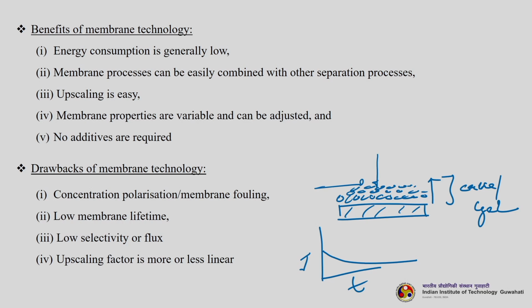So, by all these things the membrane lifetime is getting reduced, and selectivity or flux is a concentration polarization or fouling dependent thing, as it is very clear from this picture. So, selectivity or flux decreases with progression of time, and the upscaling factor is very linear.